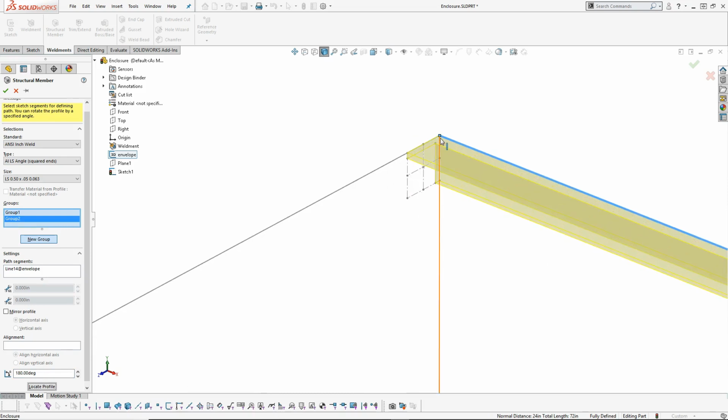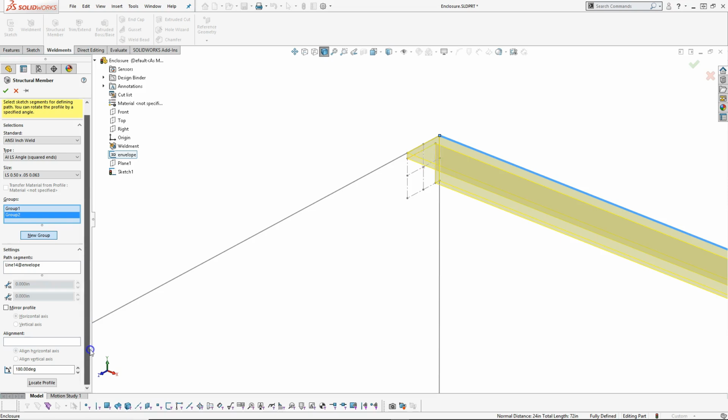We're going to the most common corner there, which is the origin, the first location, but on rare occasions I'd want to shift these to a different corner. Maybe I decide I want to put the sheet metal on the interior. Then I'm going to go back and do the locate profile, and I would pick this interior corner so that I could wrap or sandwich this on the exterior.